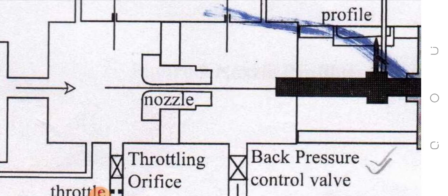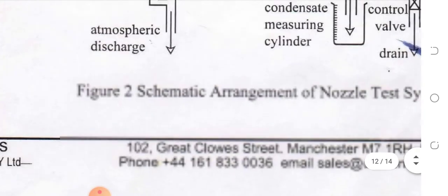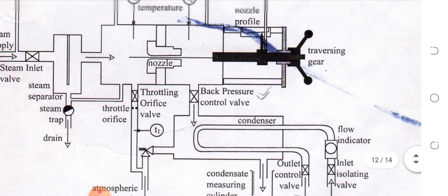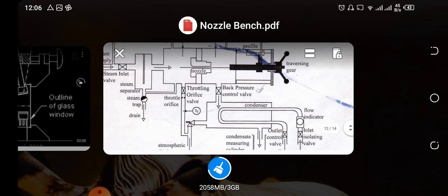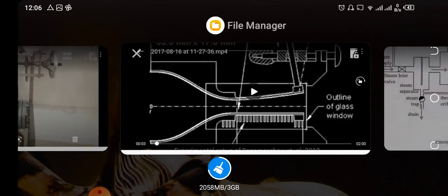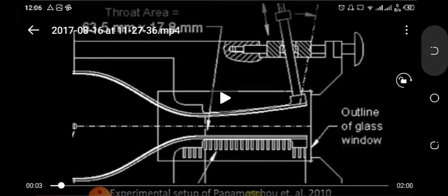So we have a number of readings, and we have to set at which point the nozzle comes into its designed position. Because if at the throat we don't have a sonic velocity, we don't have an increasing velocity after the exit of the nozzle, because the amount we increase the velocity, in the diffuser the pressure rises and velocity decreases. So the first graph happens like that. If we now move towards this video.